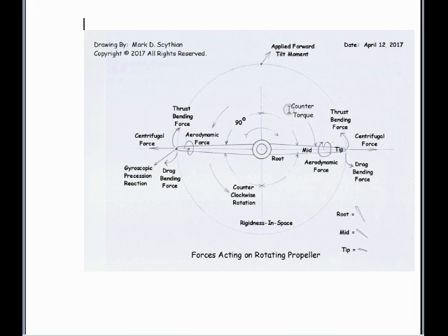So that would be airplane and helicopter applications, where the helicopter likes to exploit the precession and also the torque to an extent, because you're going to trim the anti-torque pedal inputs a little bit in the cancellation of the counter torque going right yaw, but you're actually going to use a little bit of the torque that is naturally existing to have a little bit of left yaw on the turns, along with a roll moment to coordinate that, just like on a fixed wing airplane.